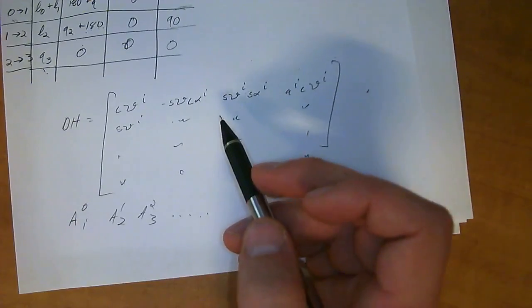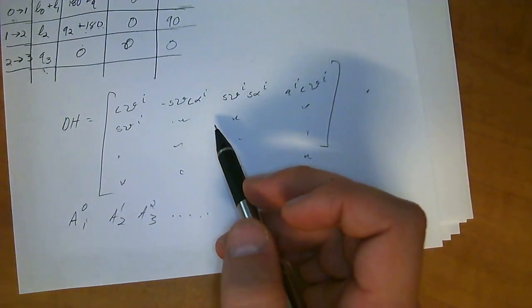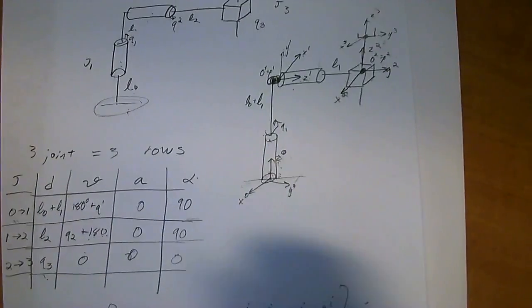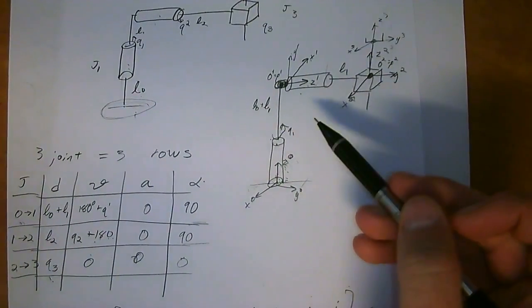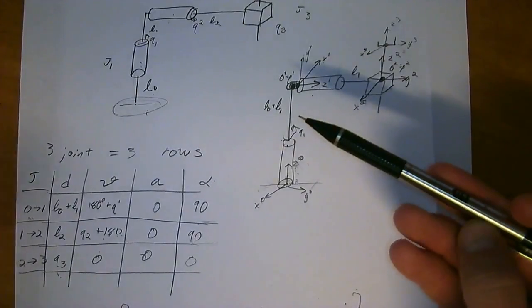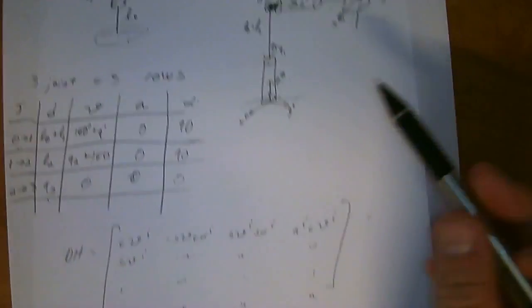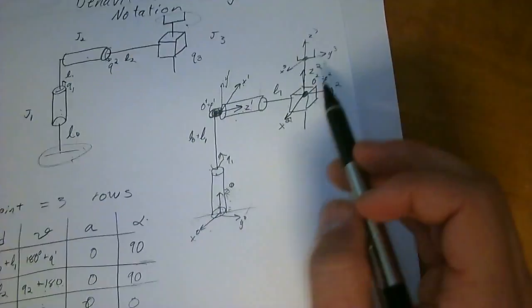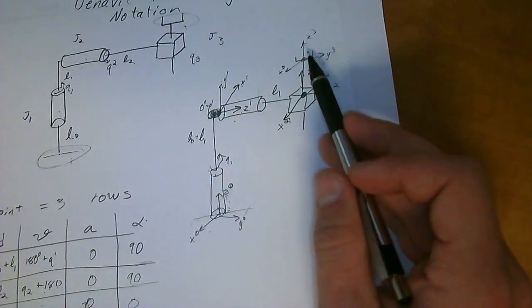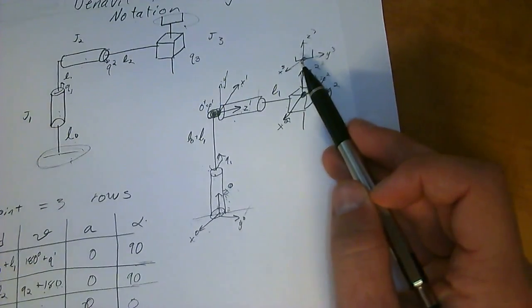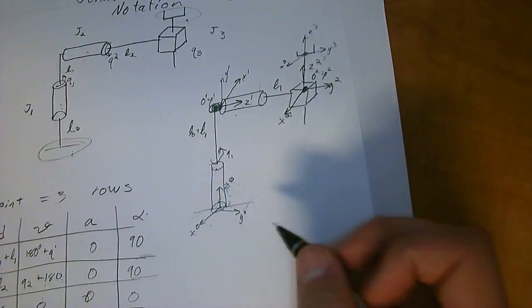From that, you're able to create the homogeneous equations and transformations and matrices in order to get a complete representation of this arm using matrices or the equations, whatever it is. But it's important to remember that we didn't include the base coordinate system or the final end effector coordinate system. Those would be a separate chunk of work that would be done using traditional kinematics.